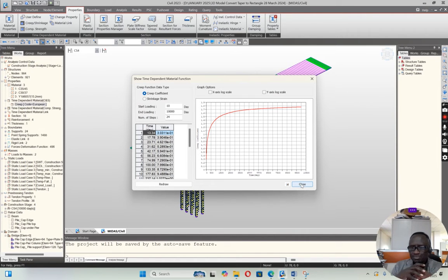So you need higher, and it's more to take care of pre-stressing and also durability, because we are trying to limit ingress of contaminants to avoid corrosion of post tensioning members that are holding those concrete members. So that is what normally is done.